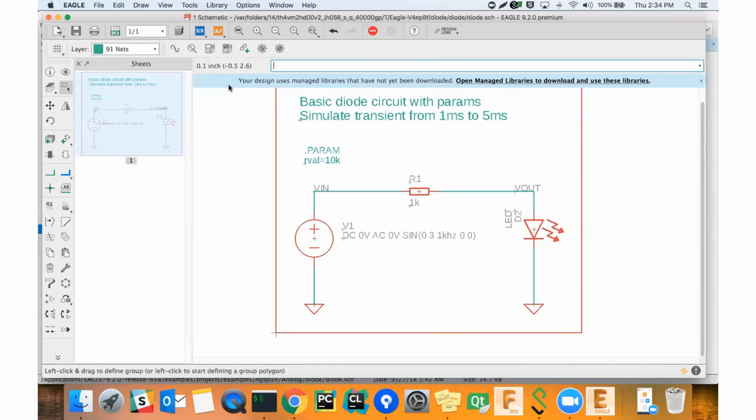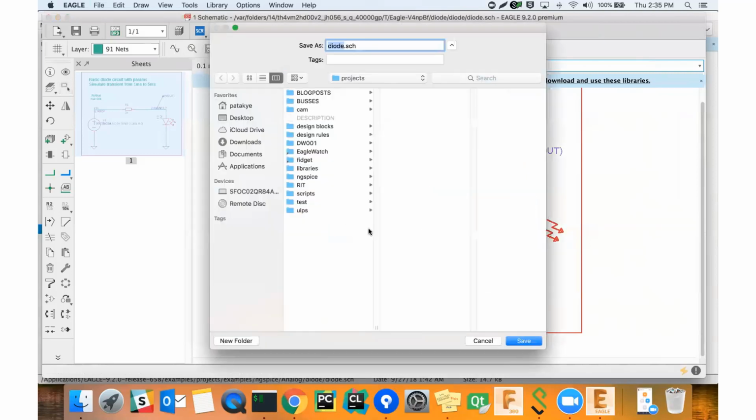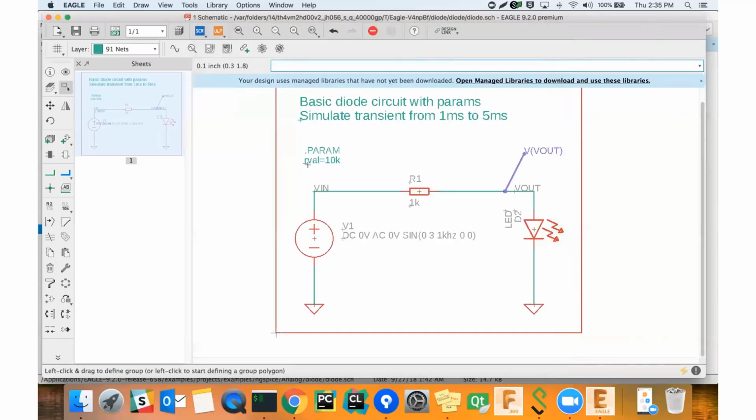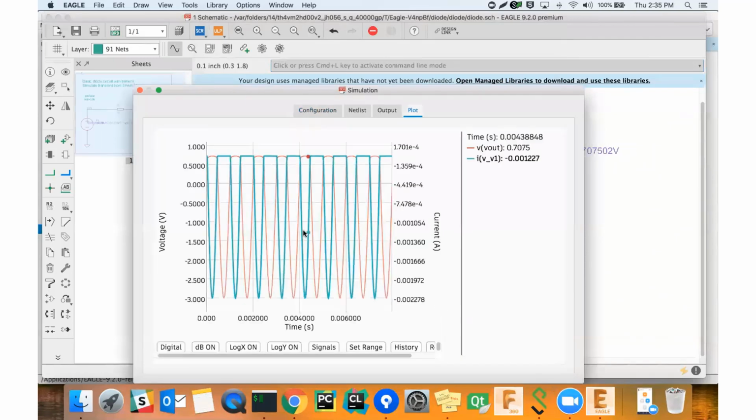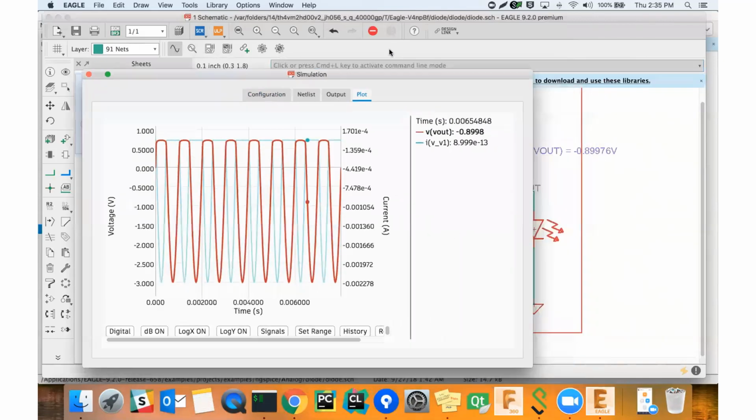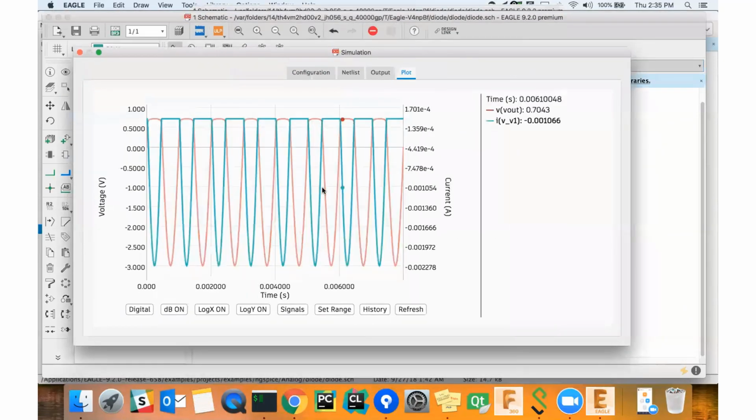So what you do is go to the simulation toolbar here and add a probe. When you add a probe, it will only look for probes. These currents for the independent sources will still be added, but you won't have the 100 named nodes for voltages. Let's say you'll have only one, the one that you put the probe on. So I'm just rerunning my time simulation, and in the plot legend, you'll see only 2 signals.